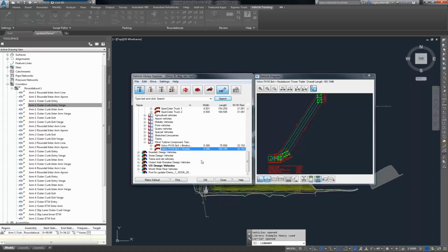Can we connect roundabout element with linear civil project to generate global report? You can if you change the assemblies we're using on the baselines we generate. If you change the assembly, it will use your assembly. We won't change the assembly being used once we've created it. We only set it at creation time, and we maintain it by updating the alignment.